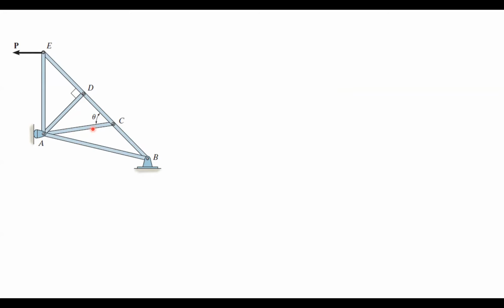So in this part, if there are two collinear members, and somewhere between those two collinear members there's a non-collinear one, the non-collinear one will become a zero force member. Remember, it's only if three members are at one joint and there is no external force at that particular joint. If there is an external force, for example, D going like this, then AD will not be zero.